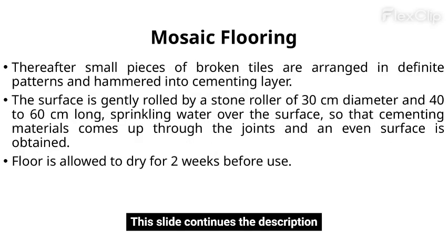This slide continues the description of mosaic flooring. Small pieces of broken tiles are arranged and hammered into the cementing layer. The surface is rolled with a stone roller, sprinkling water to bring the cementing materials through the joints for an even surface. The floor dries for 2 weeks before use.